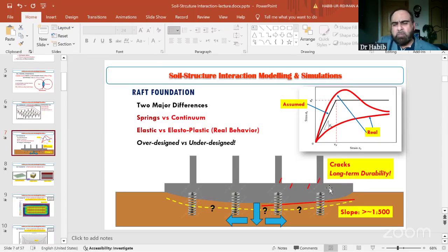But my personal experience shows that usually this problem is hidden under the ground, along the column and foundation interfaces. So to see if our structure was under designed, we should expose this part of the foundation, whether it's a raft foundation or footings, and see if there is any structural problem, such as cracks.